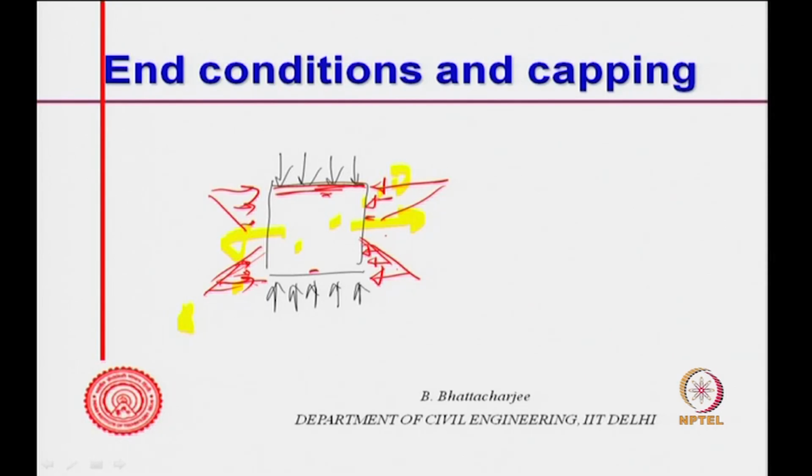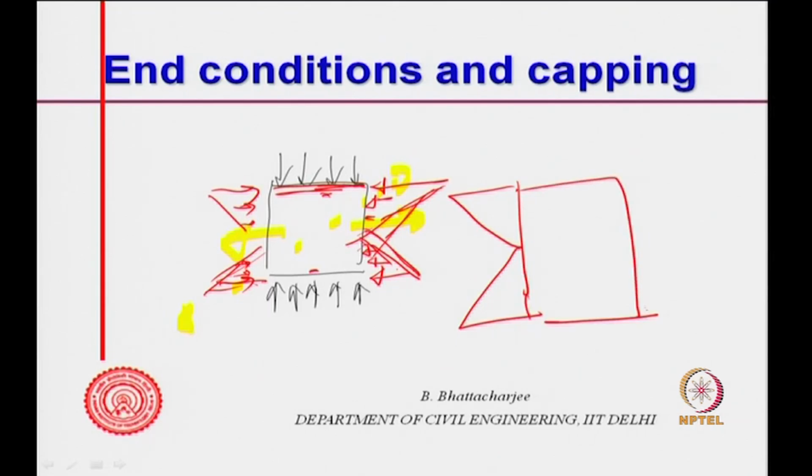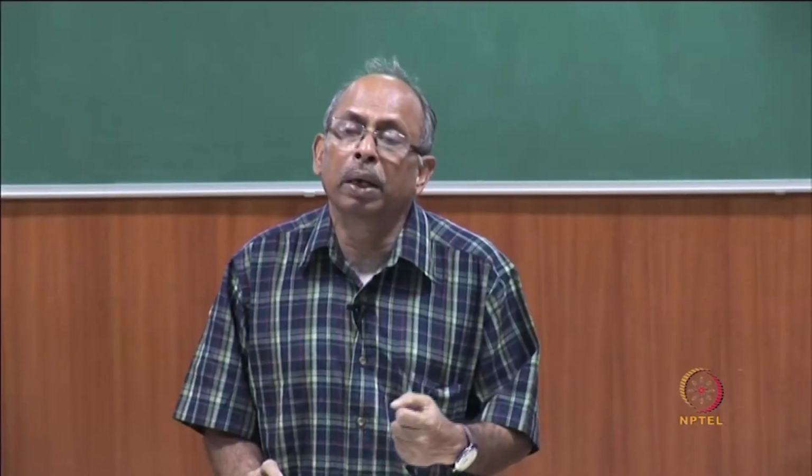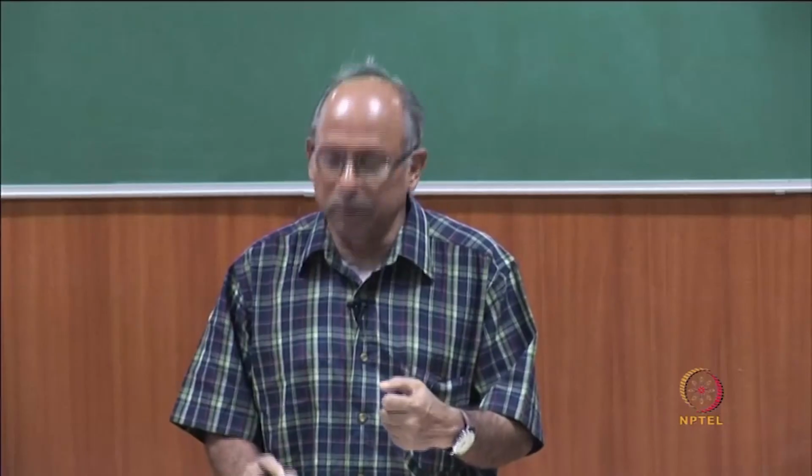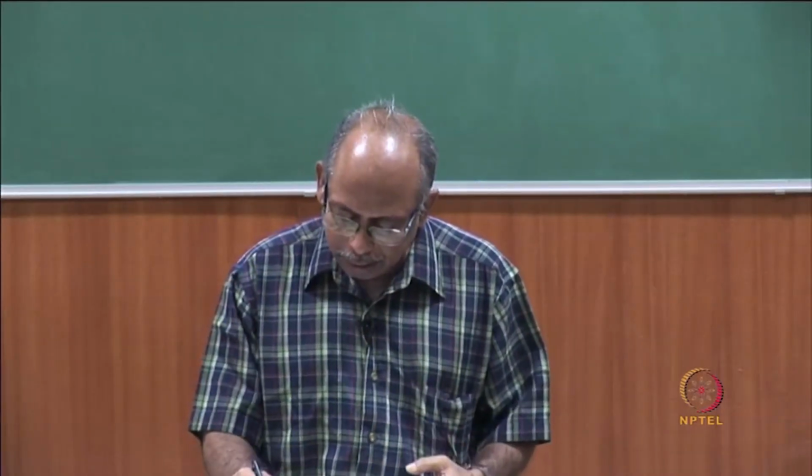So, you do not have really a purely uniaxial situation, you have a situation where there is some sort of force acting onto the specimen up to some height, depending upon the type of specimen or L by D. This will depend upon L and D, where D is the dimension of the cube. So, if it is D and D, then there is somewhat of an overlap, we will come to that just now. So, you see there is an opposing force to the horizontal or transverse movement, both in this direction as well as in this direction.